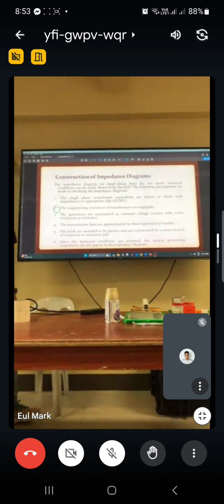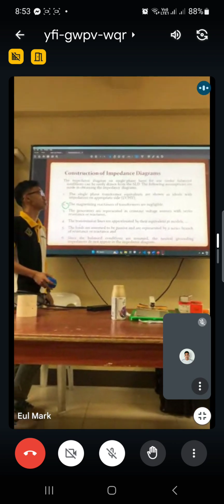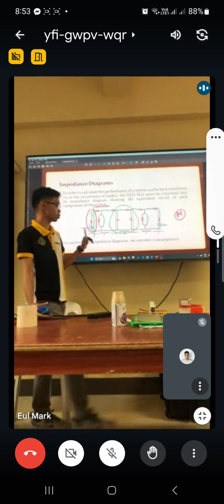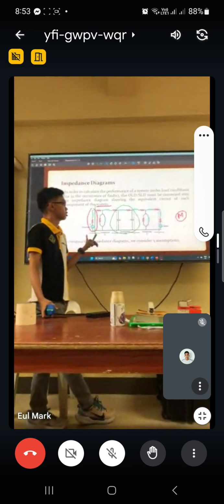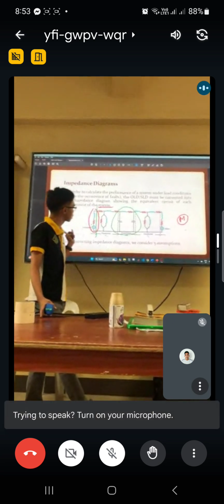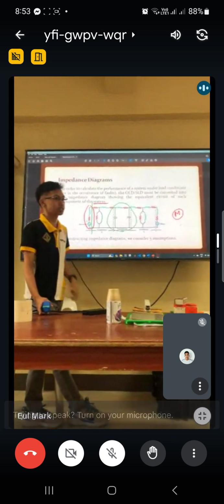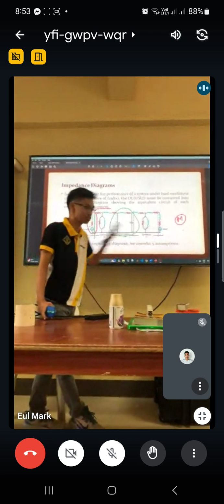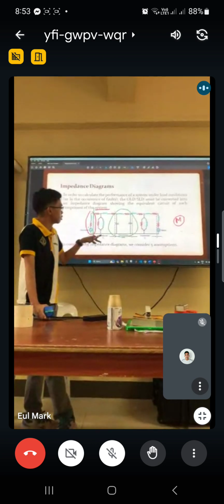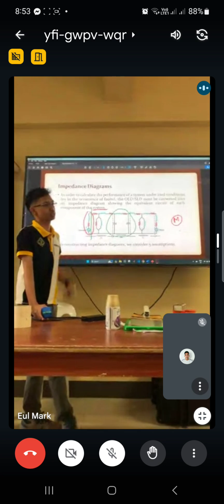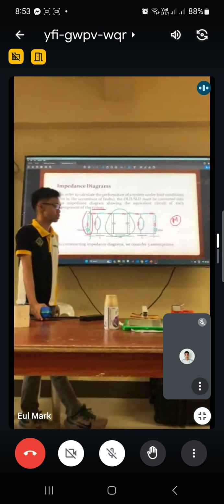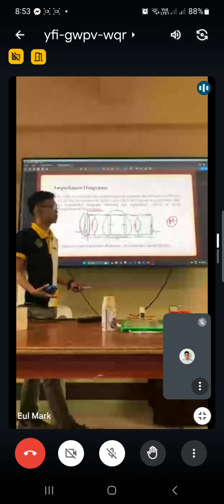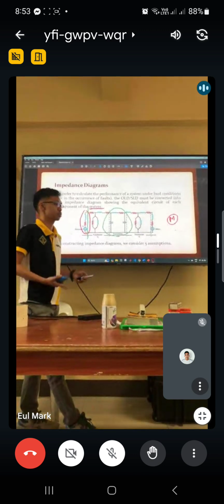And of course, the grounding circuit is not included. A transformer or a generator is usually grounded, but in this case, there is no grounding circuit. Unless it is just a reference bus. Especially for power system elements, they are not directly connected to ground.